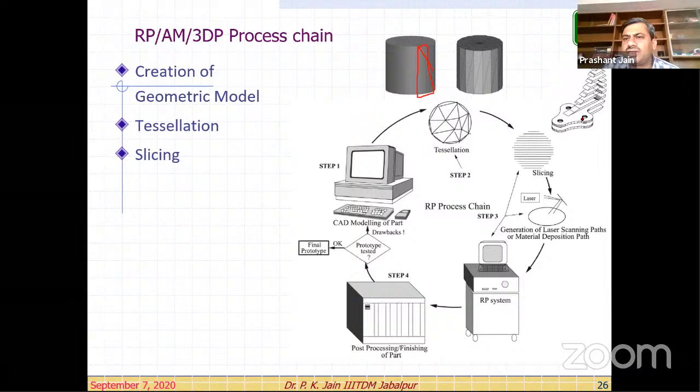Right. So this kind of tessellated surface we already talked about on the previous slide. After this tessellation, you look at this, the cross section will go like this, your plane, right? So with this cross section, what is happening now? You are calculating the intersection of this plane with these polygons, right? And here the polygon itself is a triangle, and the triangle is again converted into two lines. Look at this. Now your intersection will say these are the 2 points which are intersecting for this triangle, right?